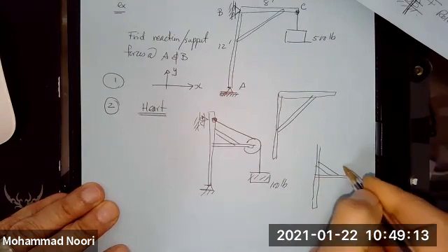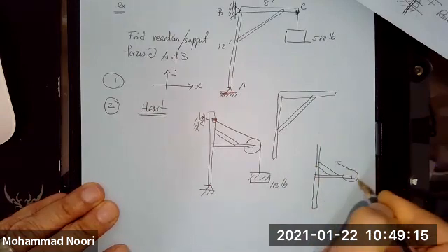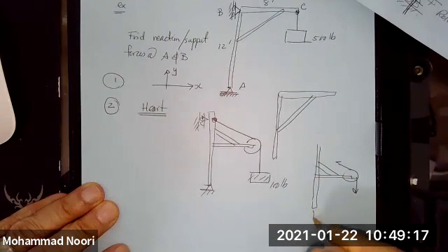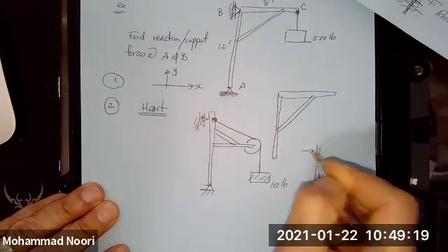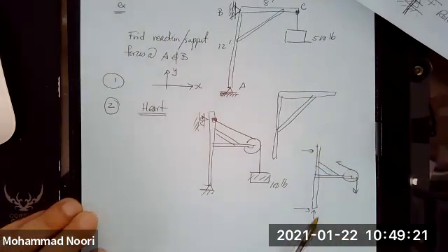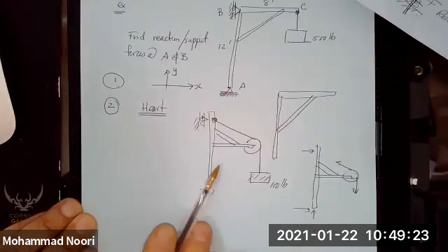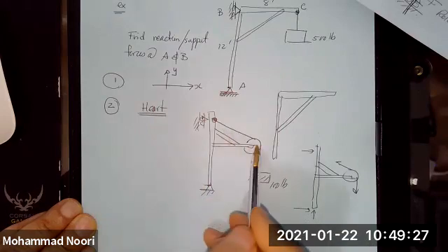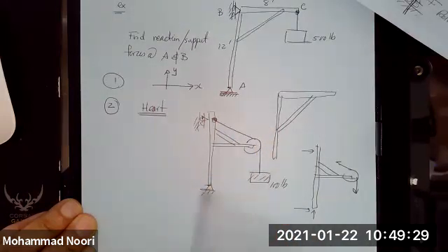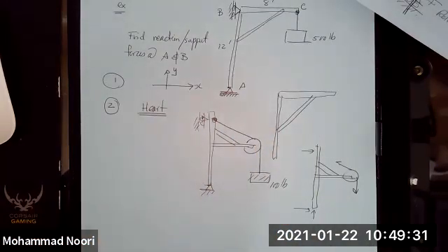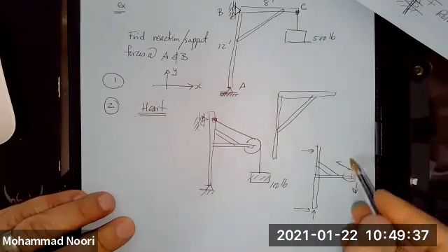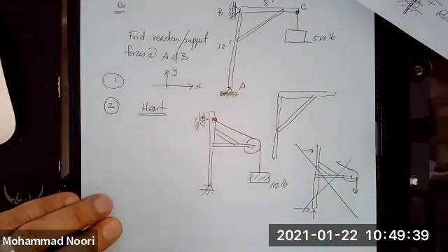Okay, you have a pulley here, so it's a pulley. I have these forces. This is wrong. When you're dealing with finding the external forces, you do not touch anything inside the structure. You think of it as just one piece. We'll get to internal forces later on. So this is wrong. Okay?